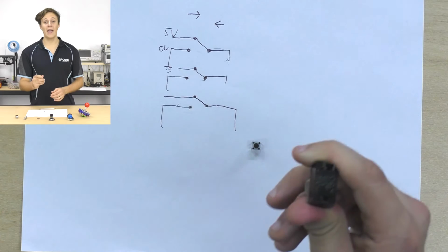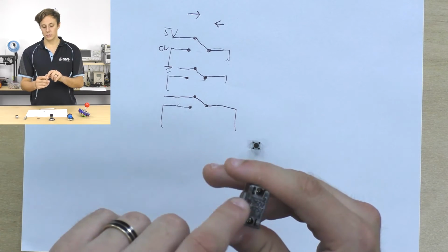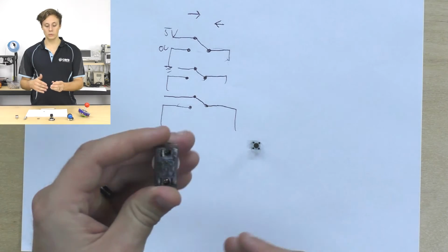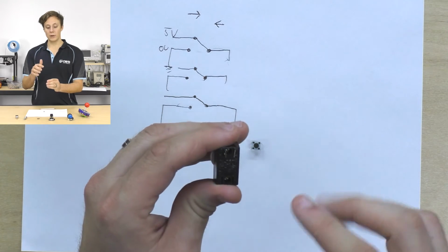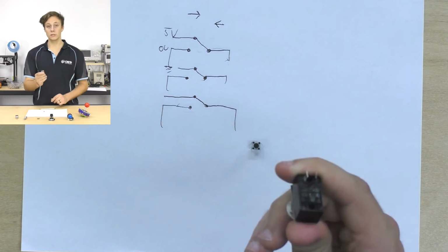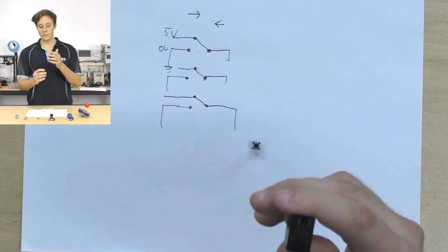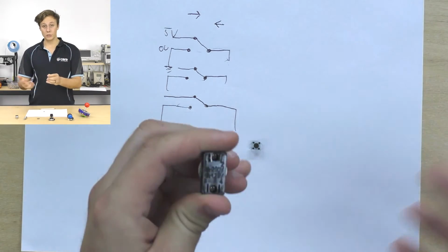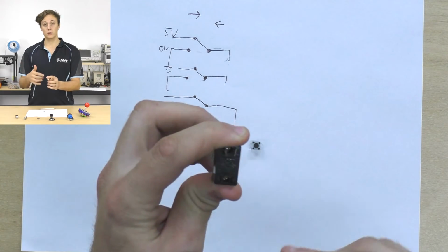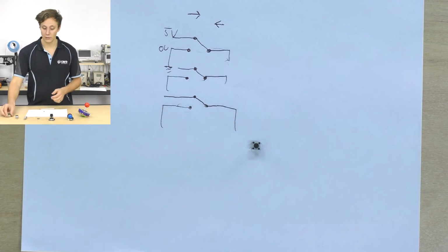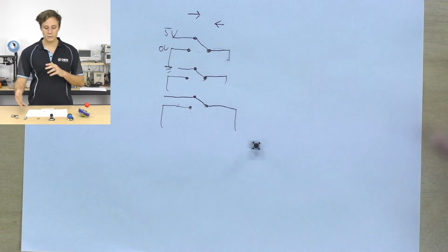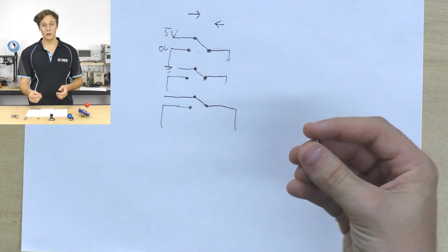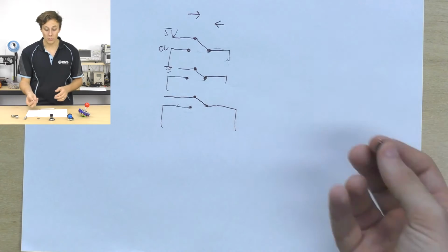So switches are rated for power. If you know power is equal to voltage multiplied by current, 250 volts multiplied by 2 amps gives us 500 watts that this switch can handle. Also, you can divide the voltage by 2, to 125 volts, and increase the current capacity to 4 amps, which is fantastic. So these are designed for handling mains current and things like that. You've got different ratings of switches. These smaller ones might only be able to handle milliamps and, say, under 24 volts or something. So ratings are really important to observe.